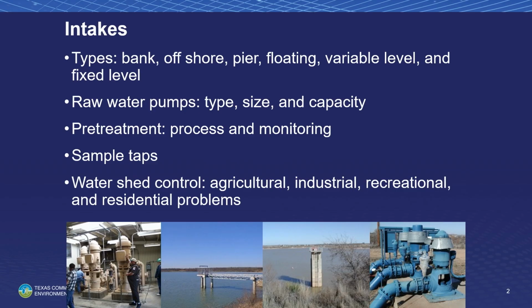So you have an issue sometimes with watershed control, point source discharges that come into your water source, particularly in areas around your intakes. If you do something like put an air bubbler around an intake to keep that water circulating, the fishermen love to come up and tie into your buoys, because all that oxygenated water draws the fish to you, so you've got issues with control, people getting in or around your intakes.